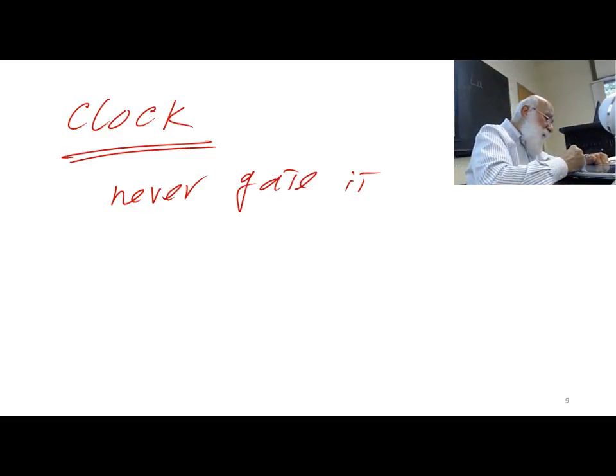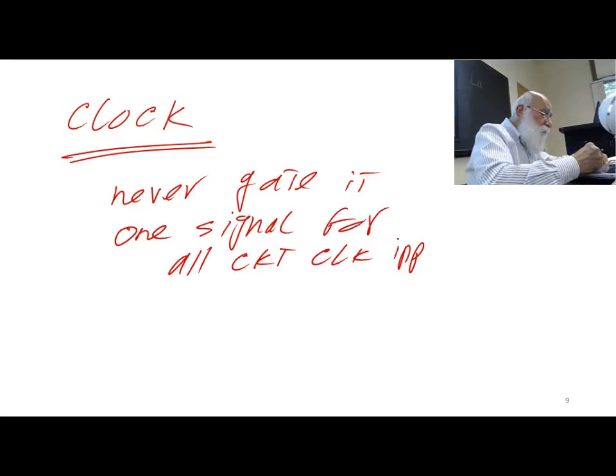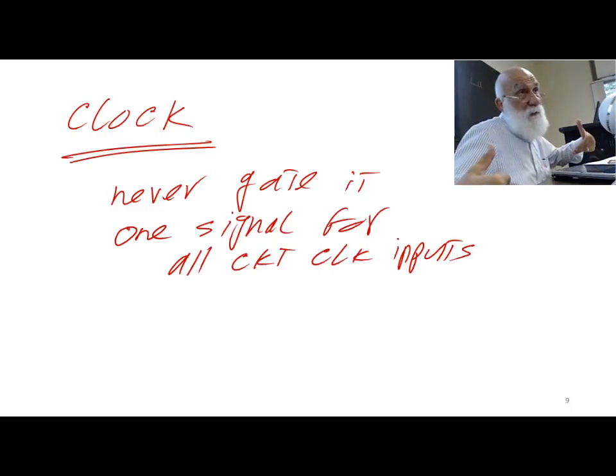I take one single signal for all circuit clock inputs. I don't play with the clock. I don't gate the clock. I respect the clock. If I respect the clock, the clock respects me.